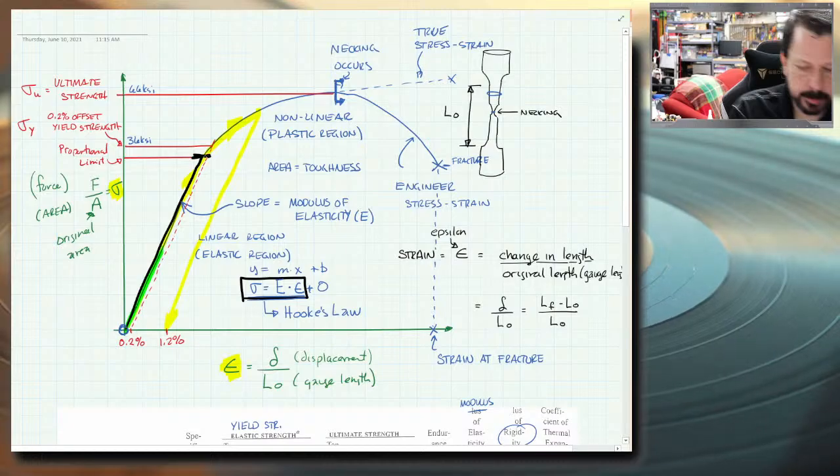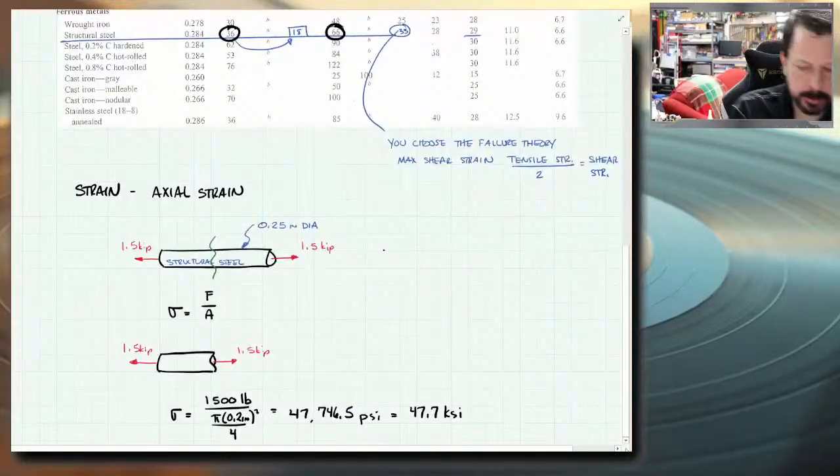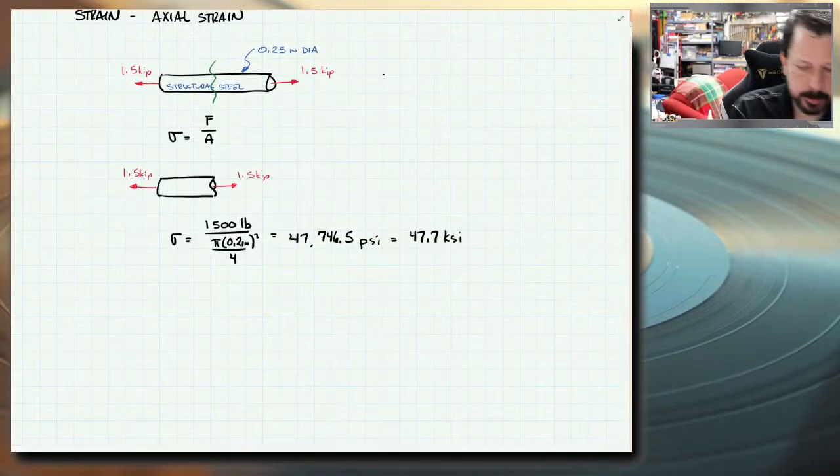Beyond that point where I'm currently at with this rod, it really is nonlinear, so it's not going to give me exactly the right amount of strain. It's going to predict something over here, right? So that amount of strain right here-ish versus being somewhere over here. So it's not going to give me the exact correct strain because I've yielded this material. But let's calculate it anyway, just to show how we could do it if it hadn't yielded.